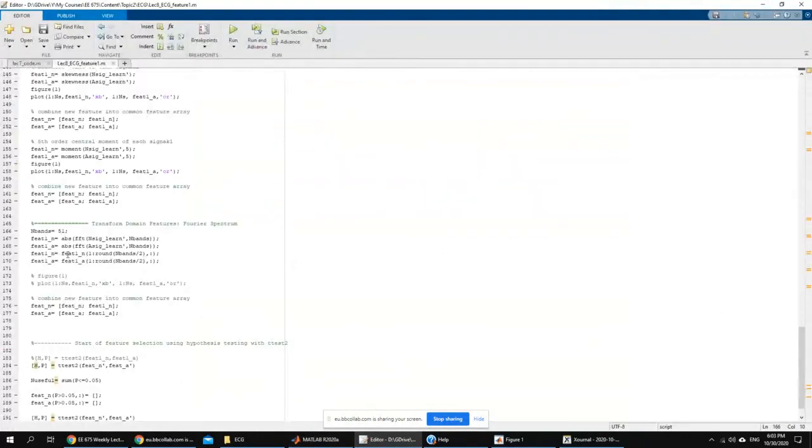As you see here, the way I divide the bands will make a lot of difference, because if you have variations between the different classes, and these variations will result in a shift in the frequency domain, a shift in the frequencies of the signal, then I better have more bands so that I can discriminate between the different variations in the signal.